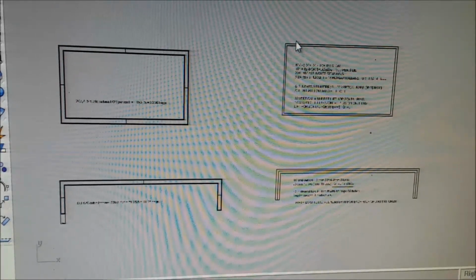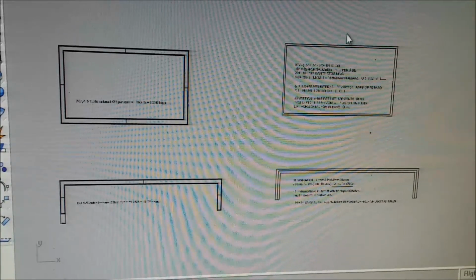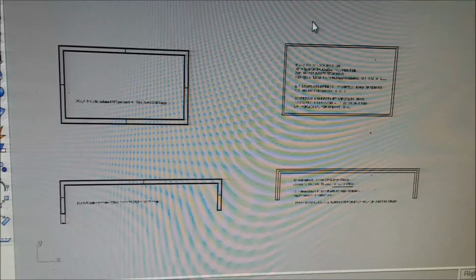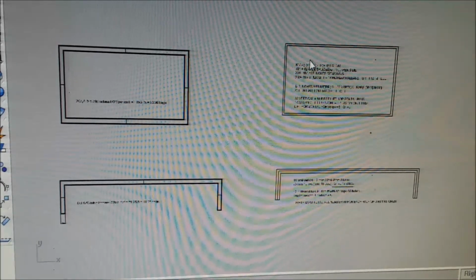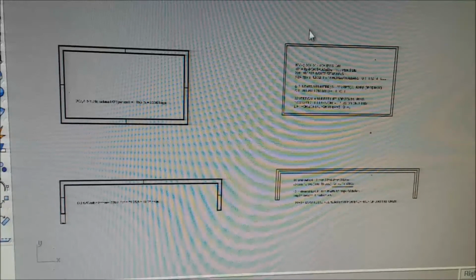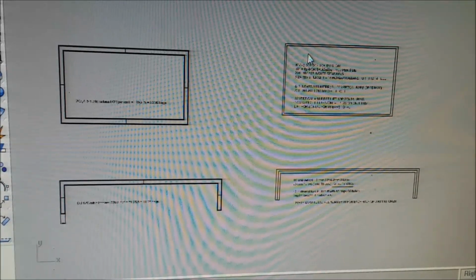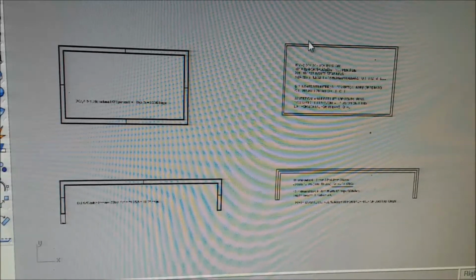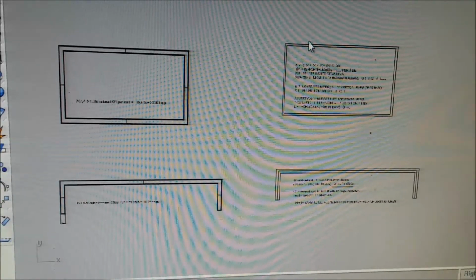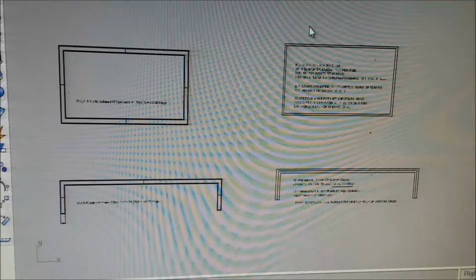And the rebars that would have gone into the post get spread through the wall, and the verticals are 1 piece from the bottom to the top, rather than about 3 or 4 pieces spliced with a lot less than 16-inch splice overlap. The best splice overlap you're going to get is probably about 10 inches. Whatever little bit is sticking up that doesn't make it out the top of the next course of block, then they stick a vertical in and it goes up another like 3 courses.